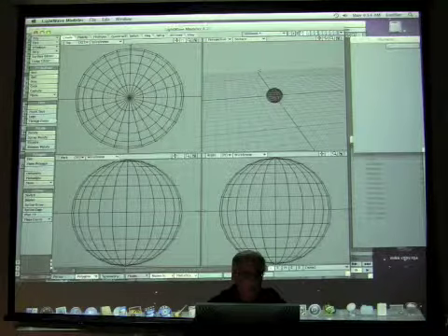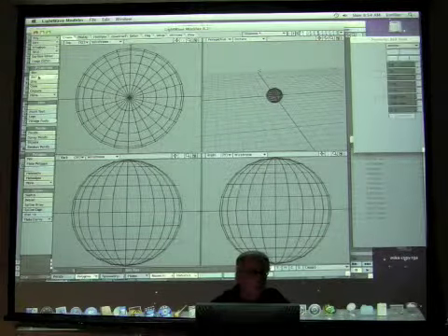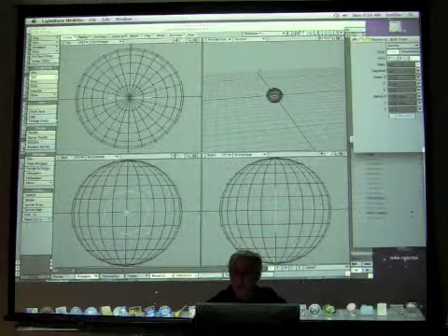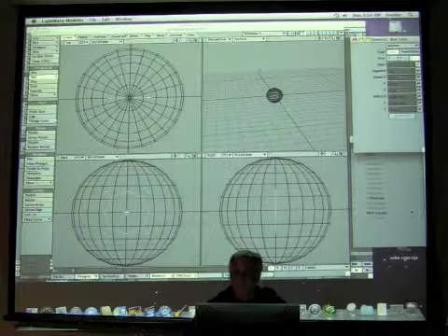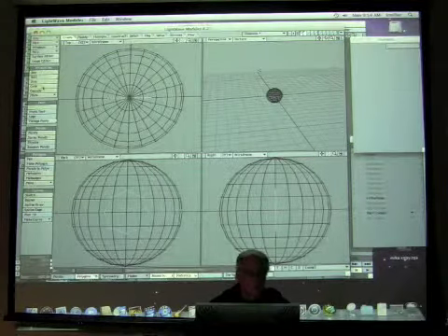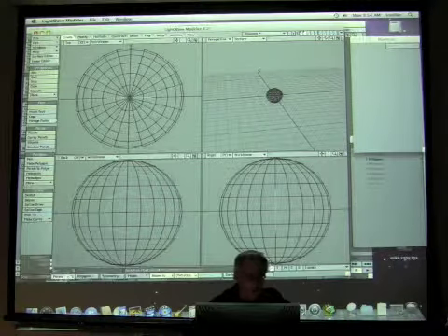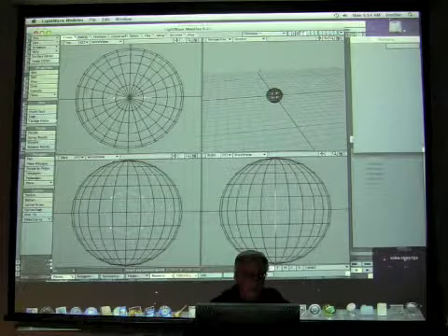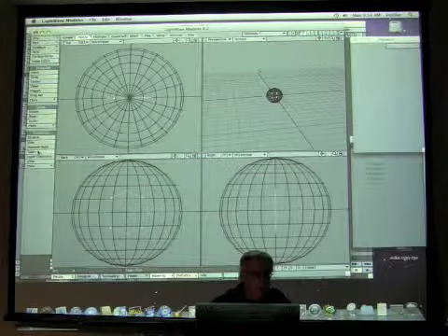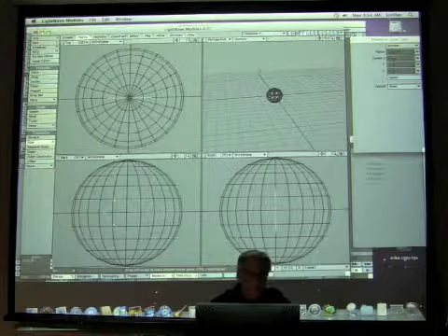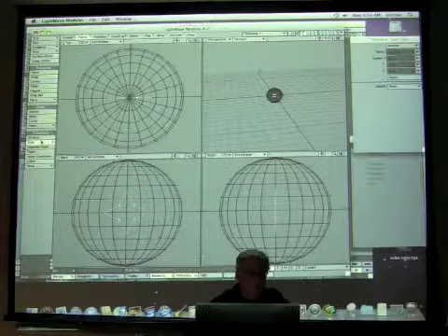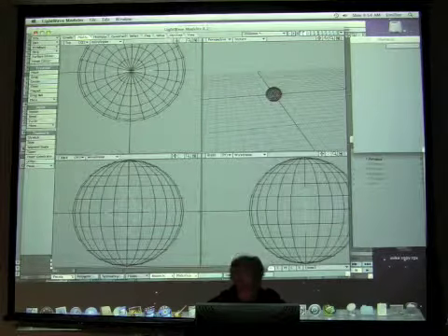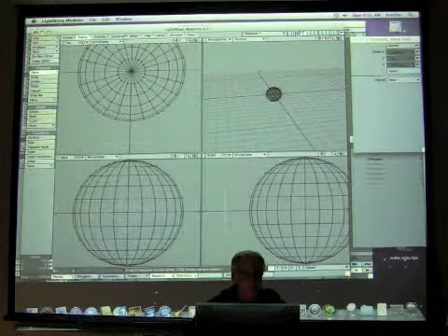Let's do this again. Ball shape. Activate. I want 8 sides. Select every other point to resize it. Notice that these are, again, on separate layers. Modify, size, shrink it in so I have my star shape. Deselect, hit T for move, and this is the important part now too. T for move, and I'm going to move this out here, like so.